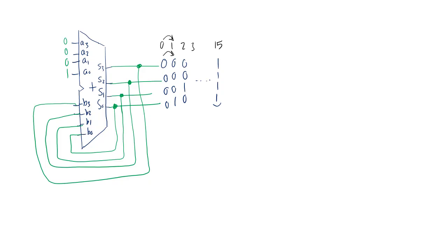Because with the flip-flops, I only went from one number to another number at the positive edge of the clock. And then by changing the frequency of that clock, I could actually slow down or speed up these transitions, right? So I could make it every second or every millisecond or a microsecond, but I had very good control over these transitions. What is really happening with this counter is that I don't have any control over the timing of this thing.